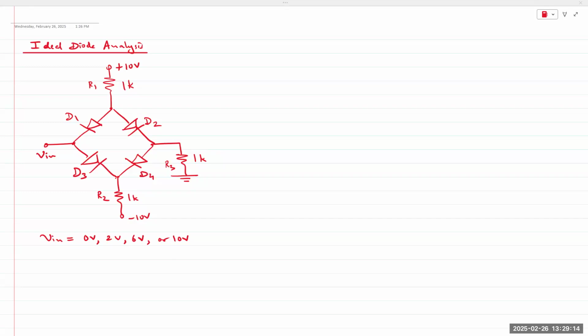In circuits, it's far easier for us to simply take a node and mark it as plus V, minus V, and reference point ground. Because if you try to connect all of those points using wires, you will have a lot of crisscrossing wires in the entire circuit. So to represent the circuit with a simple schematic, we simply do plus 10, minus 10, plus 5, minus 5, ground, ground, ground.